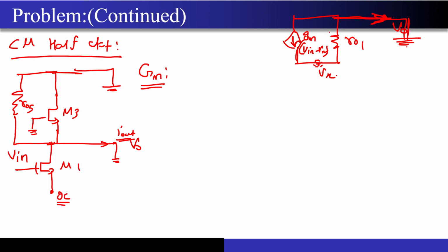And we have already seen this in the last lecture, what happens when you open circuit one of the terminals of the MOSFET. We have seen it when we were calculating the poles and zeros intuitively, correct? For the active circuits, we had seen this particular case. If you open circuit this particular terminal, this current will keep on circulating, because if any current comes out at this particular node, the KCL will get violated. Correct?